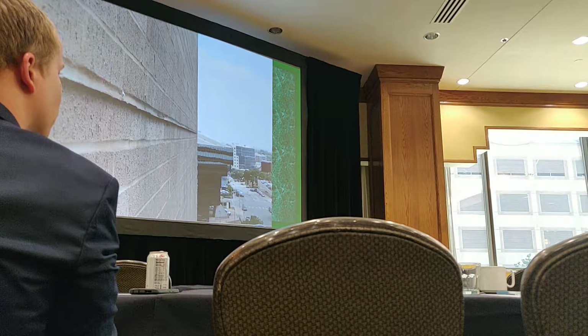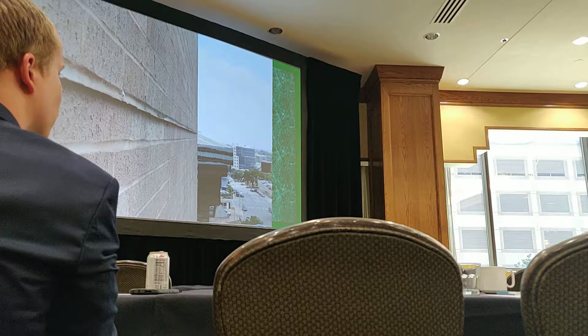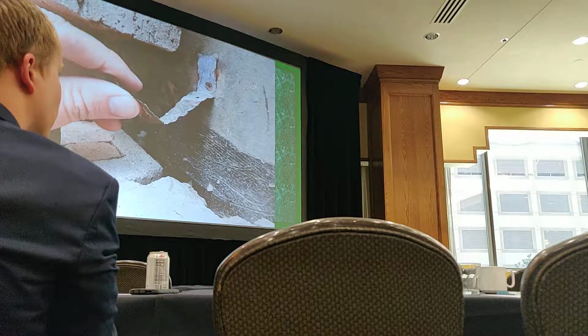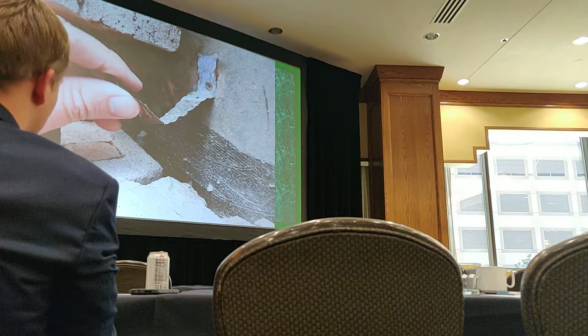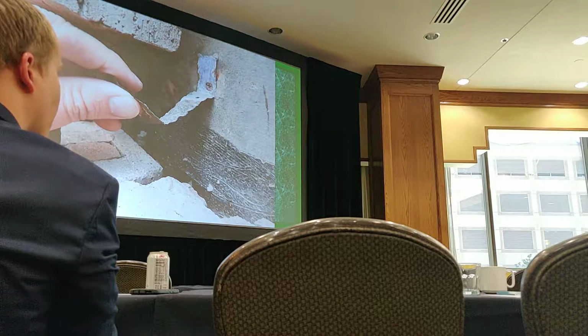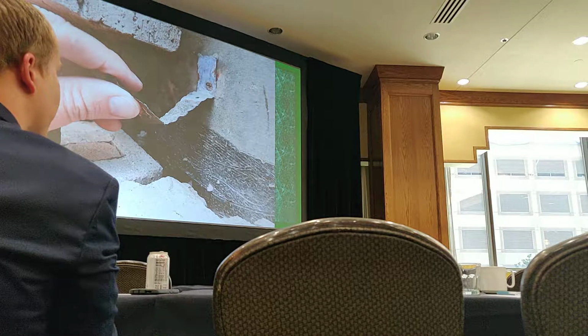The first is actually the anchor engaging the brick veneer. So, unit to anchor. This one failed in that regard. This is what was actually behind it, and these are very thin corrugated brick ties that are now see-through in most places. So the next component in the load path is you need to get it through the anchor into the backing. You can't do that if it corrodes all the way through.